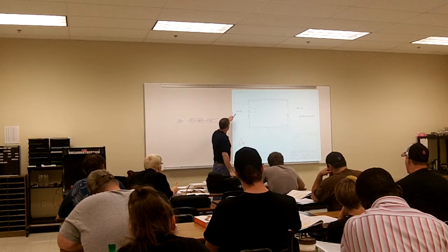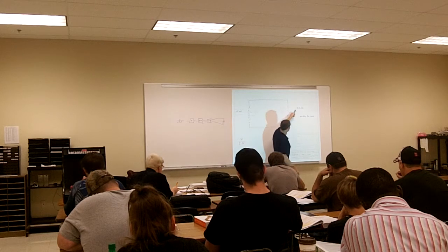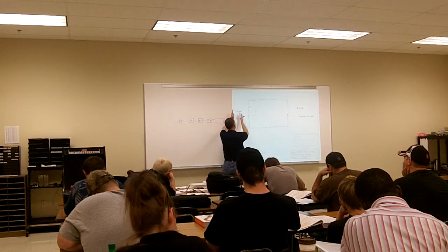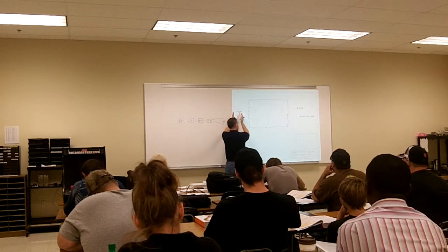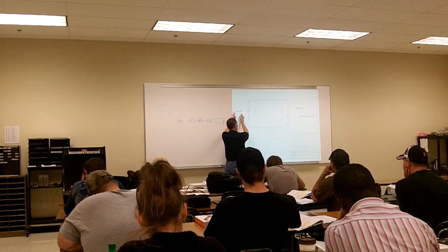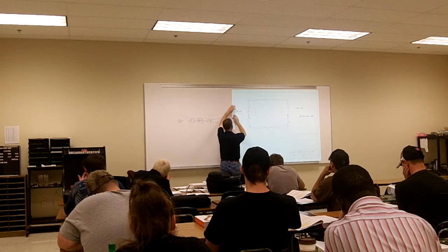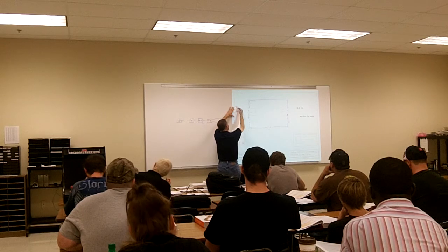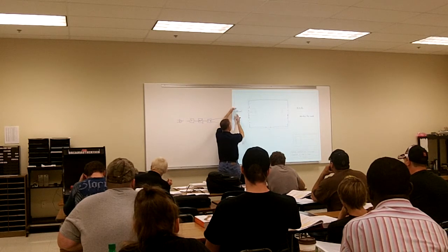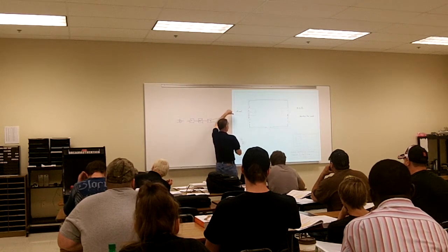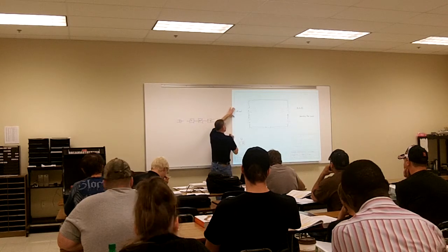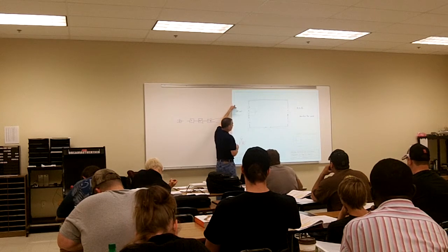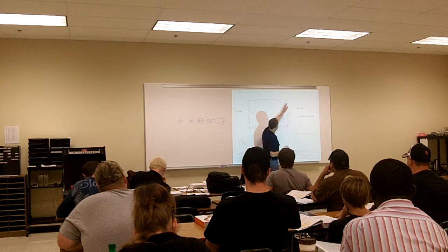So we know our voltage. We know our resistance. Now before we can figure out the rest, we need to have two items in each section. If I need to find out my resistance total and my current total, I have to have one other item in these blank areas. My resistance total is going to be the combination of all my resistors added up in this circuit.